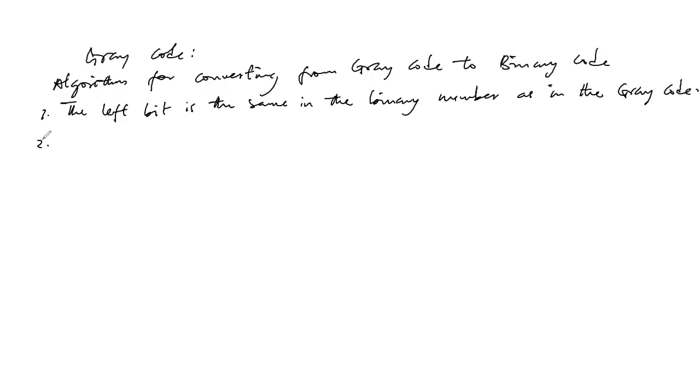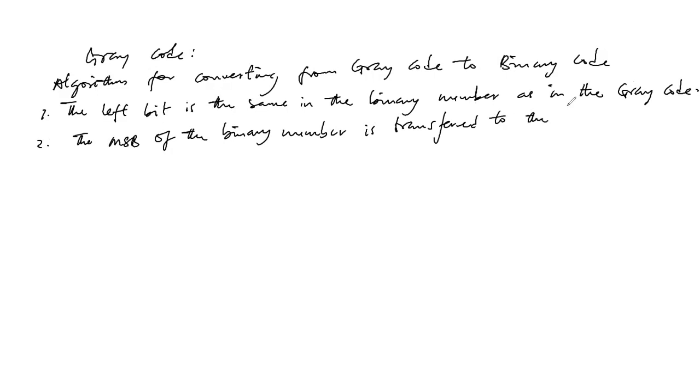The second point is that the most significant bit of the binary number is transferred to the top of the second most significant bit of the gray code.